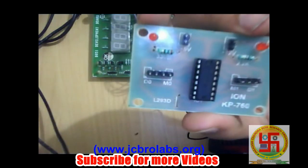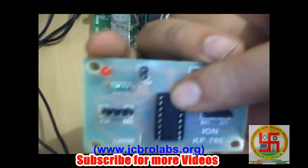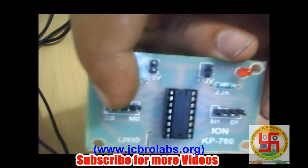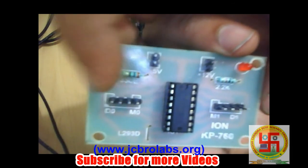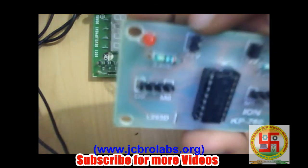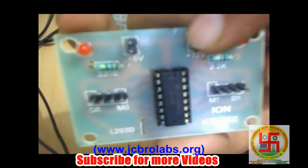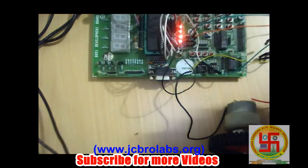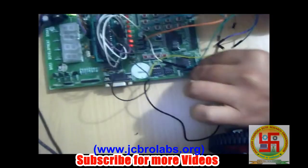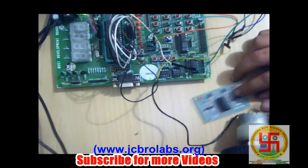So this is the PCB of the driver IC circuit. Here this is the IC, and here we have connections. These two pins are the connections for input signal from the microcontroller, and these two pins will be connected to the motor. And here we will connect a +5 supply, and here we will connect a +12 power supply. So now let's connect the connections of this driver IC circuit to the microcontroller. We will do it one by one.